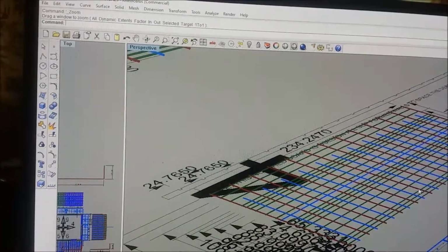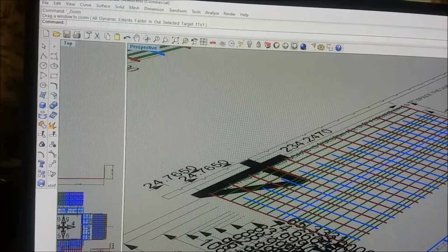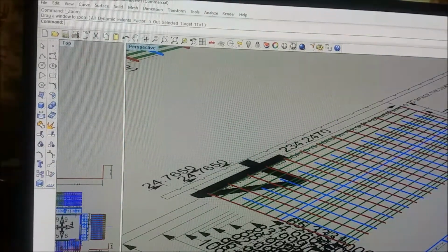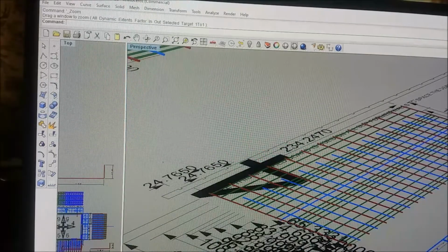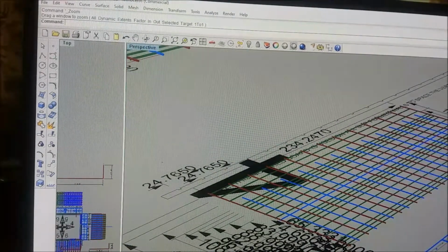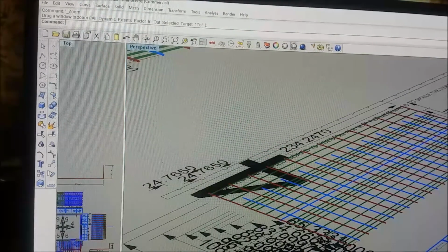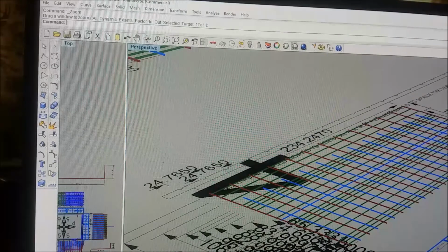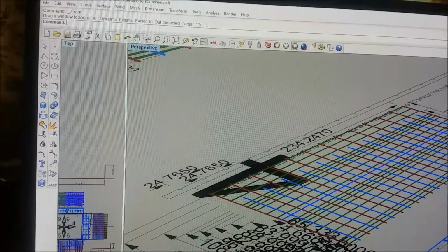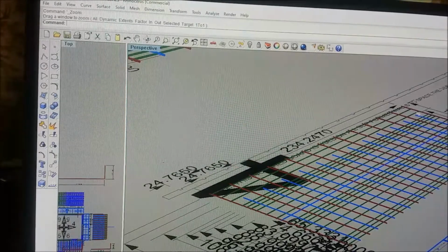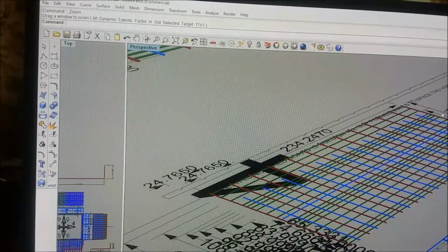Now, the bars that are going horizontal, again, back to the number 1 video of this 3-video series, they all have to stretch the same amount at any given point. So we're doing our major reinforcement as bands or belts around the thing. Down near the bottom, we have them closer together. And then they go a little farther apart. And then the slip form is going to be used 3 sets, 3 lifts. So there's 2 bars near the edge of the first lift, 2 bars at the start of the next lift, and then at the top up here, we do the same thing. So we get the full height, 4 foot of the form, and then we use the bottom hole in the top, and we get 3'6" and 3'6", and that apparently comes out to 128.9997 inches of wall height.